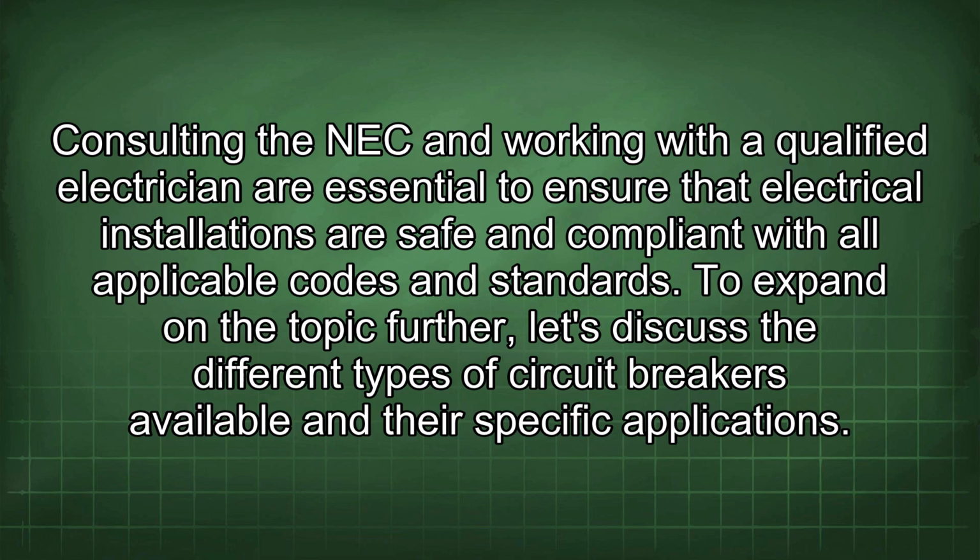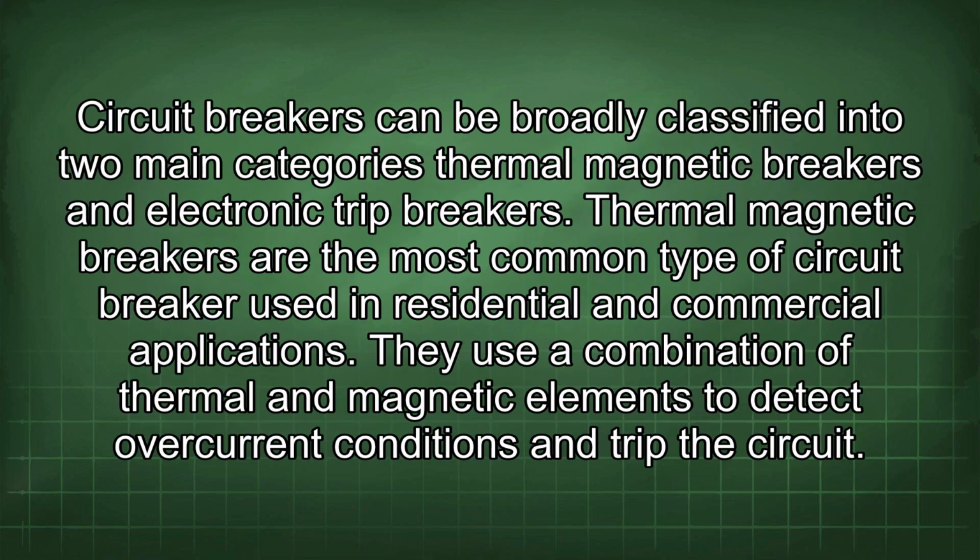To expand on the topic further, let's discuss the different types of circuit breakers available and their specific applications. Circuit breakers can be broadly classified into two main categories: thermal magnetic breakers and electronic trip breakers. Thermal magnetic breakers are the most common type of circuit breaker used in residential and commercial applications. They use a combination of thermal and magnetic elements to detect overcurrent conditions and trip the circuit.